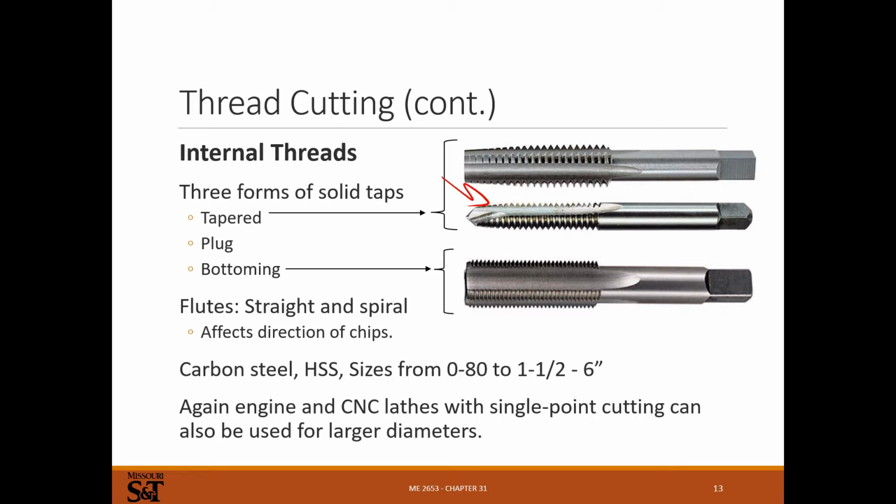And these are made out of high-speed steel, or really high carbon steels, and they're really strong. Usually a lot harder and stronger, and a little more brittle, than whatever material you're trying to tap. If you break a tap off in, it can be very difficult, if not impossible, to remove it. These things are brittle, so when you try to get them out, they'll usually break into pieces instead of coming out intact. You can't really machine it with anything because it's the same material that your machining tools are made out of.